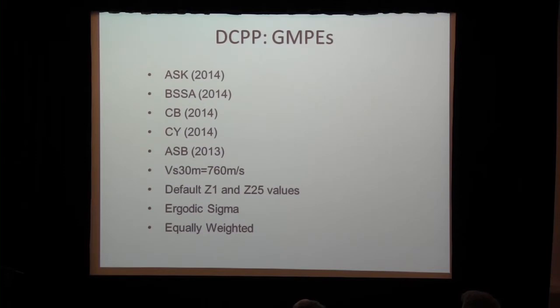So from the ground motion team, we had to come up with 2 different types of source classes that are controlling the hazard at Diablo Canyon. One is, of course, the vertical or nearly vertical dipping strike slip faults located very close to the plant. And then you've got all the reverse faults that we've seen some presentations on, and we'll see a lot more in the next 2 days, that are basically right next to the plant, or the plant is sitting on the hanging wall side.